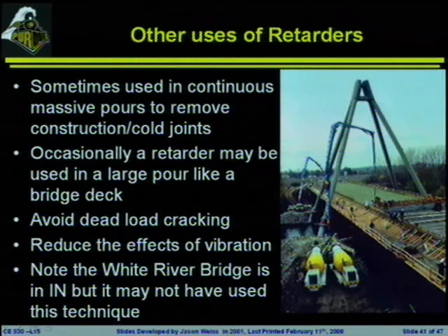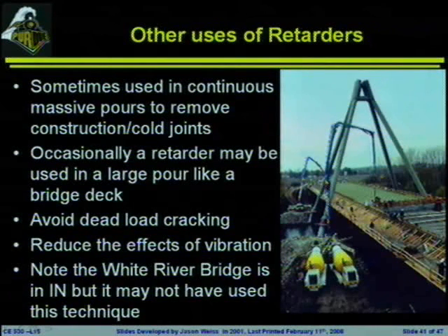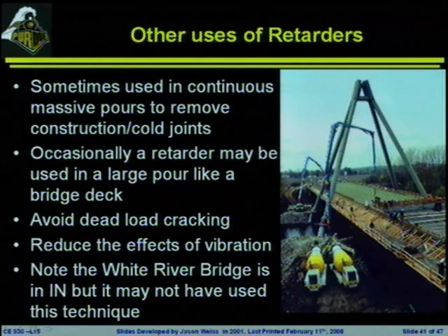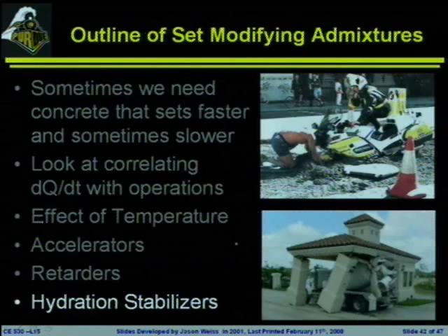One of the reasons why people may want to do this is because another reason, in addition to vibration, is the dead weight of a bridge deck is going to be putting stress onto the rest of the deck that's already there. So if you don't get the entire weight of the system on before the concrete sets, you're going to be flexing that very, very fresh concrete. So they want to try to avoid flexing that concrete when they're starting to put more and more weight on from the bridge deck. So this is a way for them to avoid the dead load cracking and reduce the effects of vibration by causing it to set somewhat uniformly.